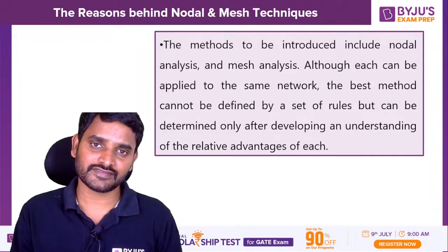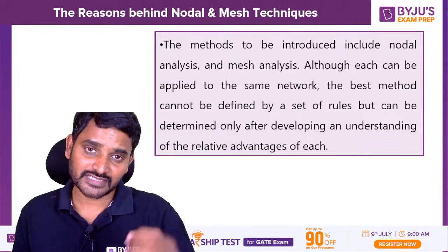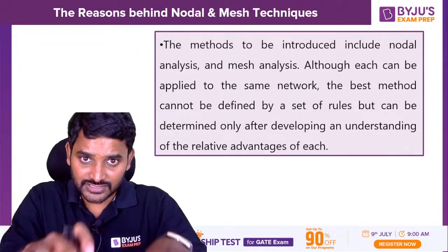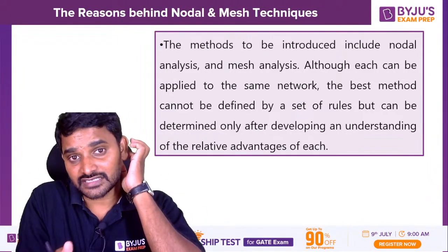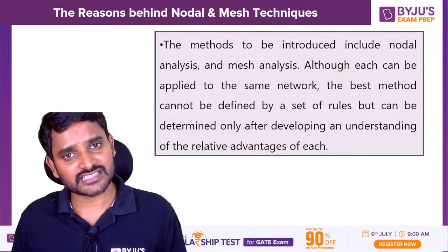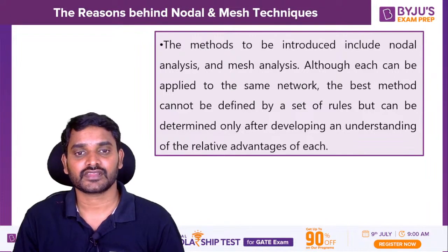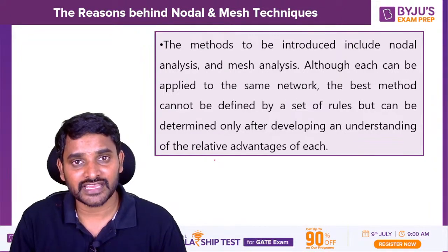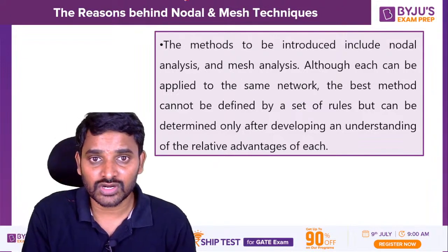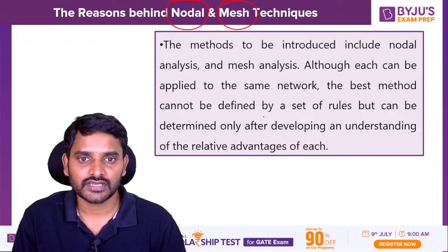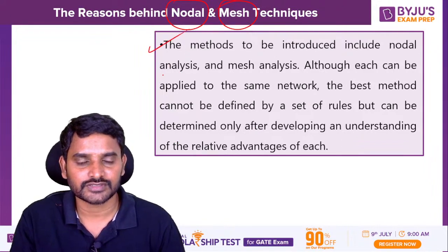By implementing a method on a particular network, the method by which you get a quick answer is the best method. In some cases nodal will be the best, in some cases mesh will be the best. So until you solve the network by applying a method, you cannot decide whether nodal or mesh is the best one. That is what this point is about.